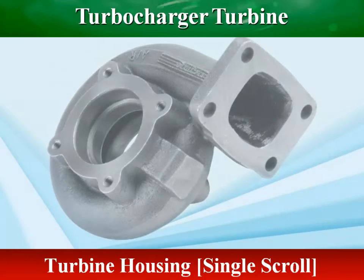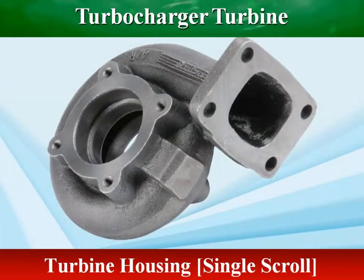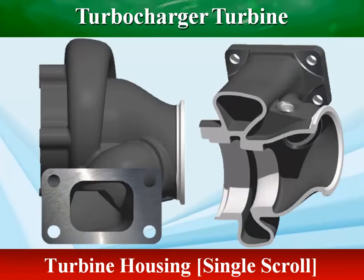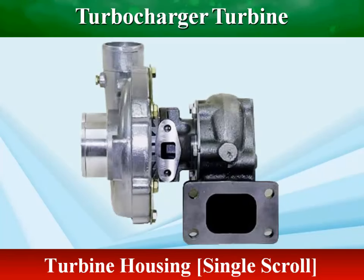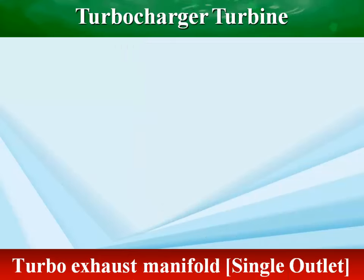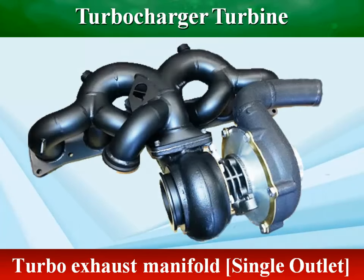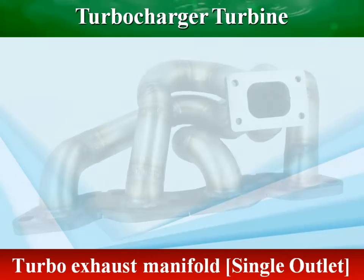In single-scroll turbos, all exhaust gases are channeled into the turbine housing through a single entry, spinning the turbine wheel. Not as efficient at scavenging exhaust gases compared to twin-scroll turbos. A turbo exhaust manifold collects exhaust gases from an engine and funnels them into a single outlet to power the turbocharger turbine.